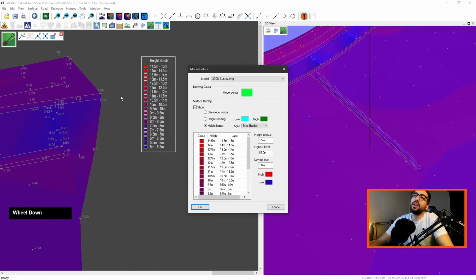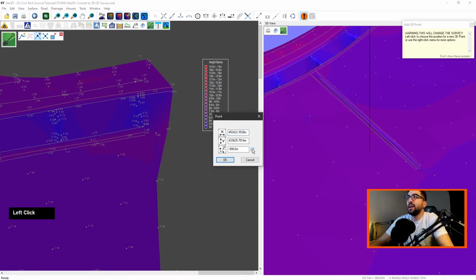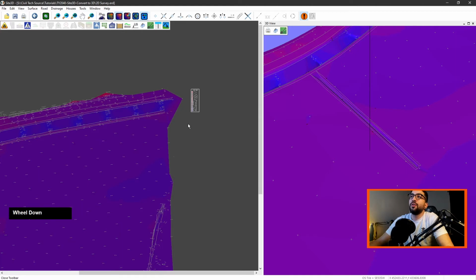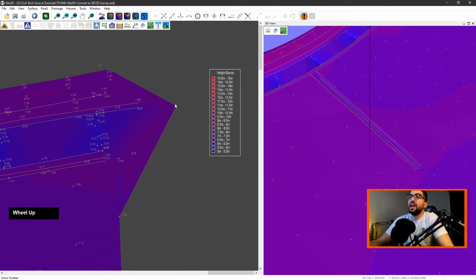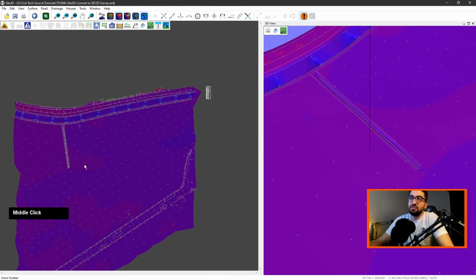I don't know how they coded the location. I think it's top right of the boundary by an X amount extent. So actually let me test it. I'm still on my surface edit, so if I add a point, let's say here, and I'm going to add the value, what's the closest one, let's say 8, hit OK. Yes, it moves it. It picks up the boundary of your model, and then what it does is add an offset to it at the top right corner. So that's good to bear in mind.